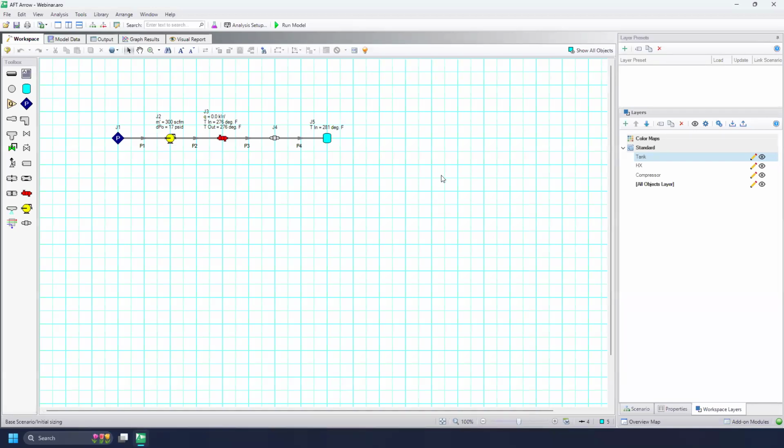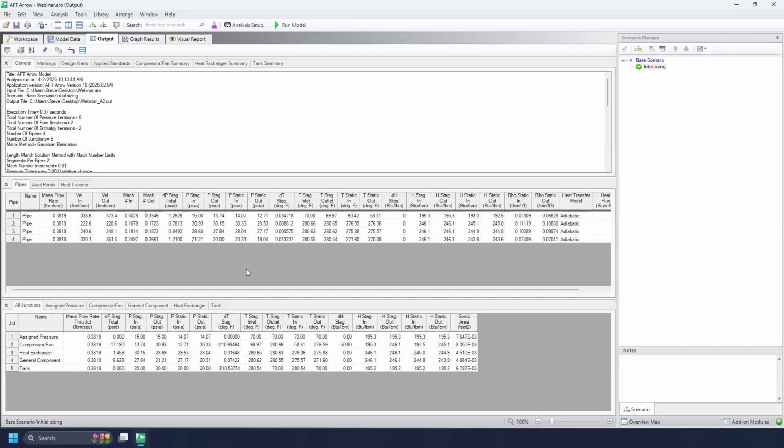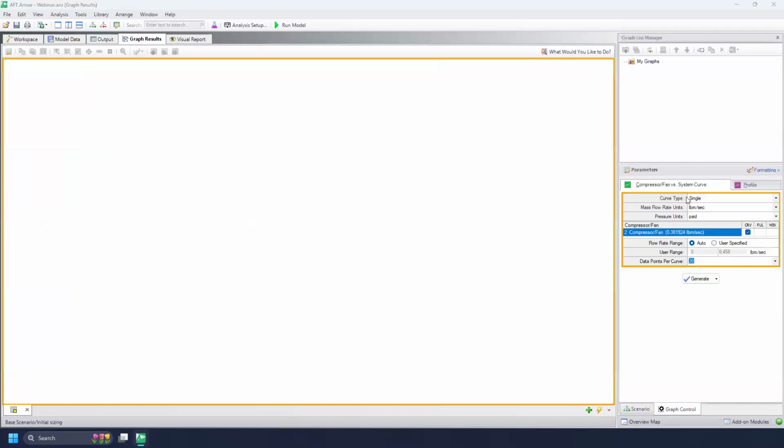We can see that this is a hot flow going into this tank. We may want this lower, which is why we have the intercooler. And we'll get to that in a second. Other things that we can look at here. Let's go ahead and see what's going on with the Mach numbers. Okay, there's no sonic choking tab up here. You can see none of these Mach numbers are going to 1. So it looks like we're not close to sonic choking.